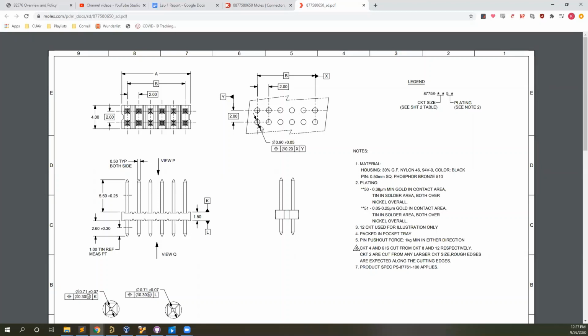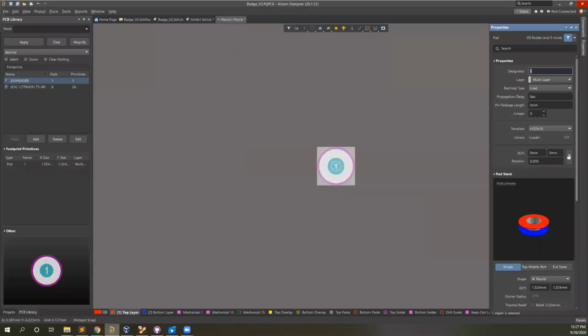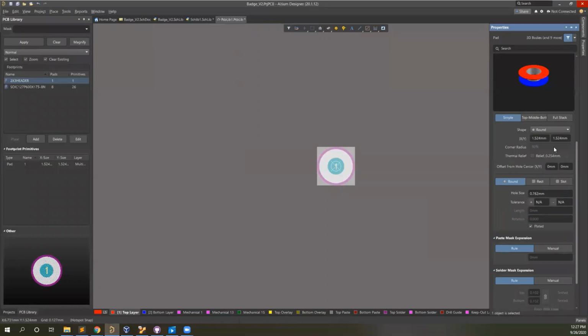And also remember, in manufacturing, the more holes you have that are the same size, the cheaper your board is going to be to manufacture. So if you have a different hole that's a similar size, maybe stick to that size. But for now, we'll just give it a little bit bigger than it currently is, maybe 1.1 millimeters, for instance. Yeah, let's do that.